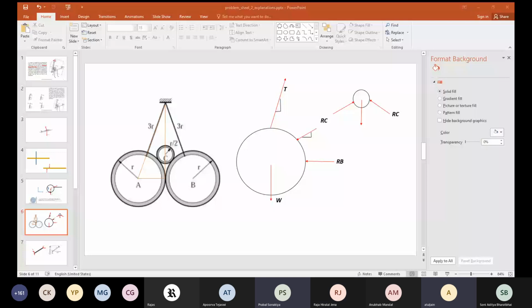Can there be an equilibrium like that, when there is a little gap between A and B and C just holds right there? Can the body be in equilibrium if A and B are not in contact? So for that one tiny phase, it will be yes. For some value of WC, that will be in equilibrium. That is the maximum value of WC that is possible.